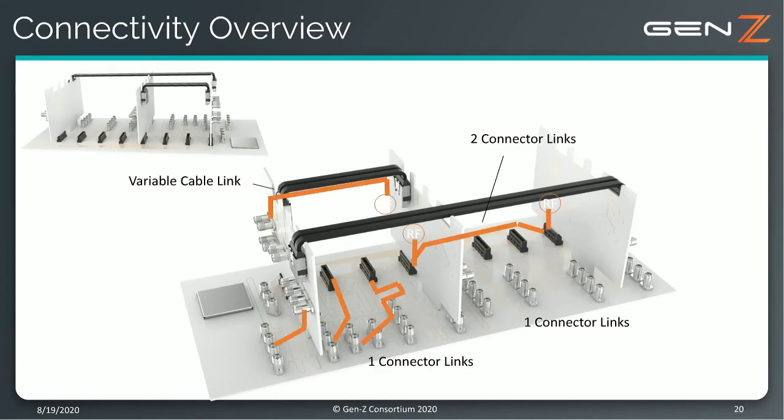On the next page, you can see where those connections are made. The cable interface with a short route to RF connectors is highlighted in orange. Also highlighted in orange are card-to-card connections through the PCB backplane, passing through two connectors. And then also in orange is what the one connector interface would look like, through the backplane to one of the connectors and onto the plug-in card.